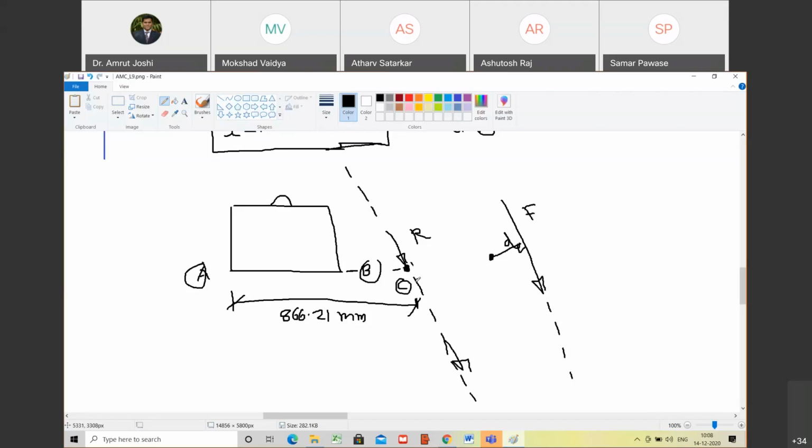But wherever I shift this resultant along this line of action, that line of action is going to pass through C. Therefore, wherever I put the resultant along this line, its moment about C is going to be 0, because the perpendicular distance between C and its line of action is 0. So it is not the only location where I can have only the force resultant of this force system. You find the resultant at any point along this line of action, and you are going to get the same result. Are you with me? Yes, sir.